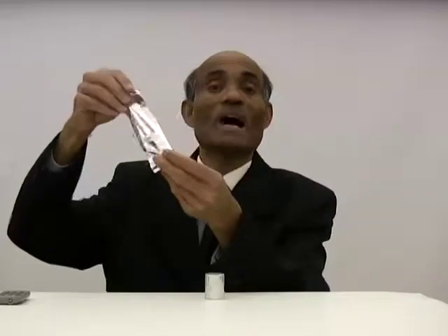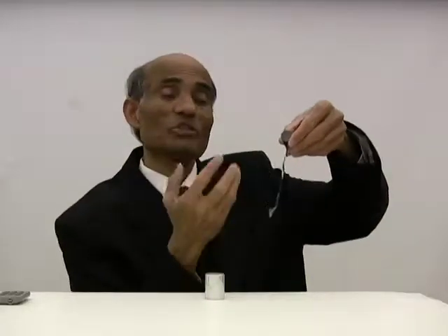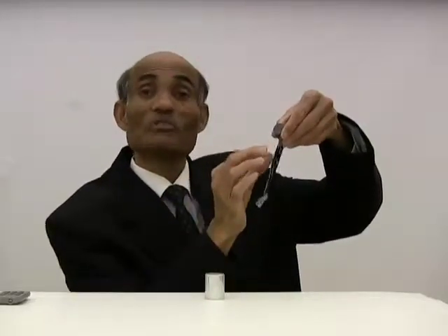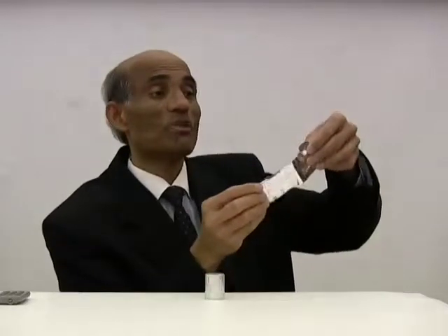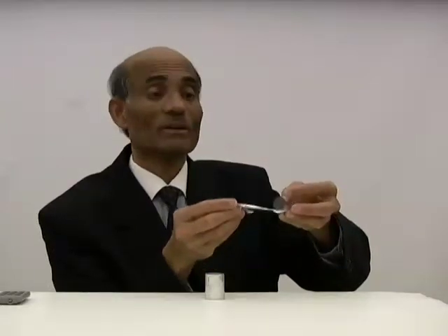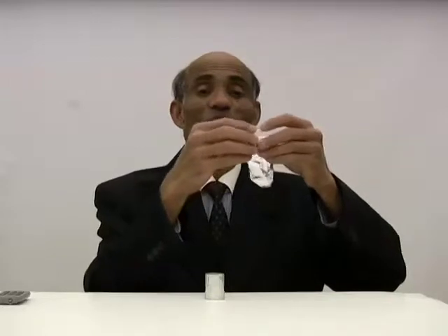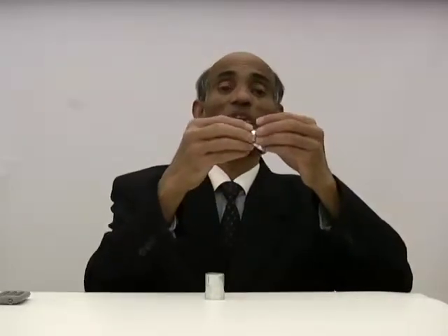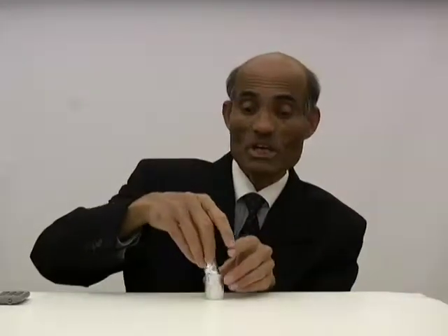It is rolled so that the dielectric, you see, you have a dielectric in between. A thin sheet of paper, and you roll it up. Why do we do this? To increase the plate area. So you can construct your capacitor like this. You can use a very large area of the conducting plate, a very thin plate, and then separate them by a thin dielectric. We can construct very large capacitors.